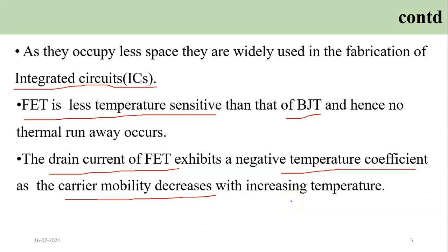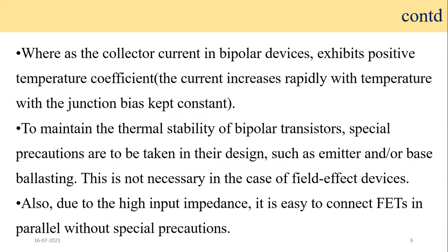So the drain current of FET exhibits a negative temperature coefficient, whereas the collector current in the BJT exhibits a positive temperature coefficient. This is another very important difference between FET and BJT. The reason being, with increase in the temperature, the mobility increases. That is another important thing.